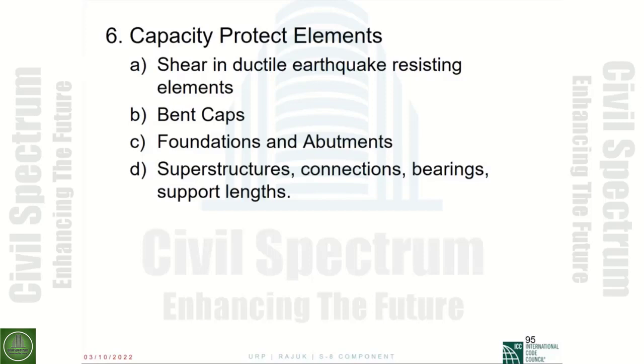We have the guide specs for the seismic design. That will be displacement based. You need to do more detailed design and more detailed analysis for the concrete and for the steel, the curvature analysis, and all of these, to make sure that the actual displacement capacity is less than the demand displacement. And we talked about the steps of the design. You have to select, you have to design, and you have to protect. So these are the main elements that we have.